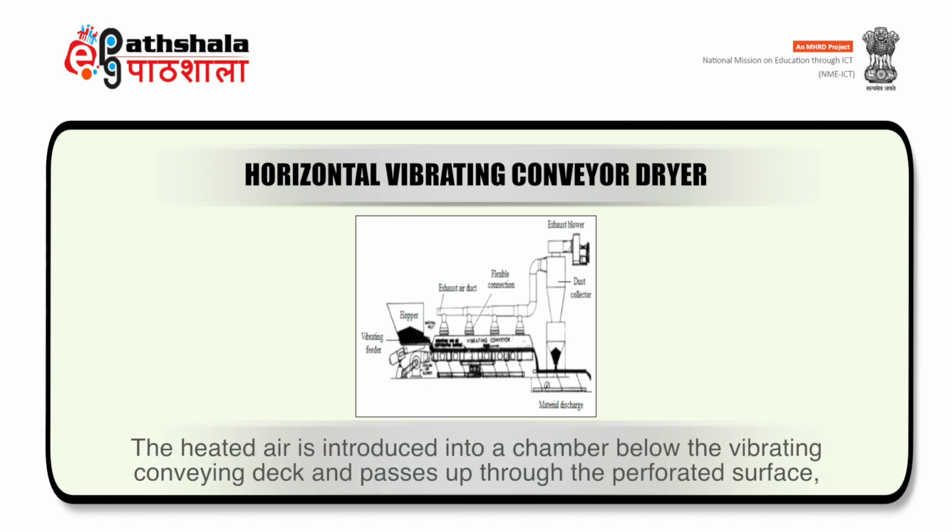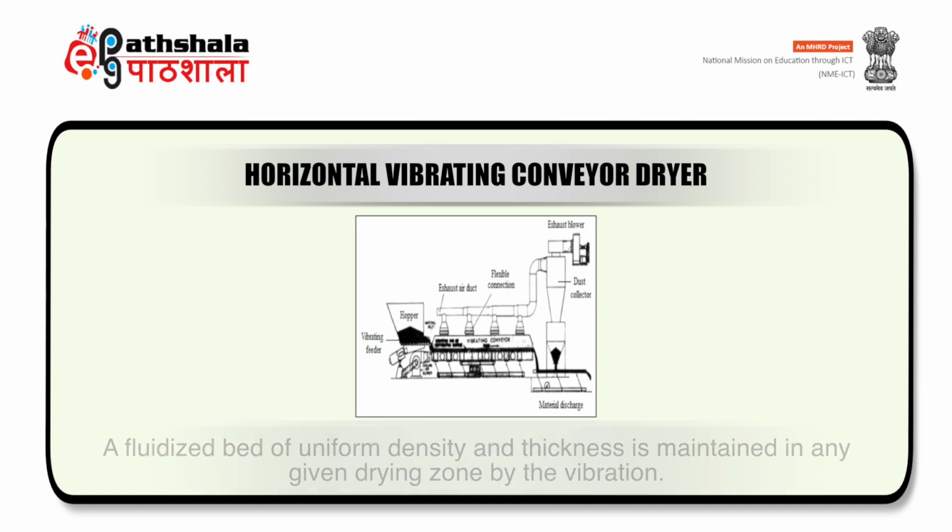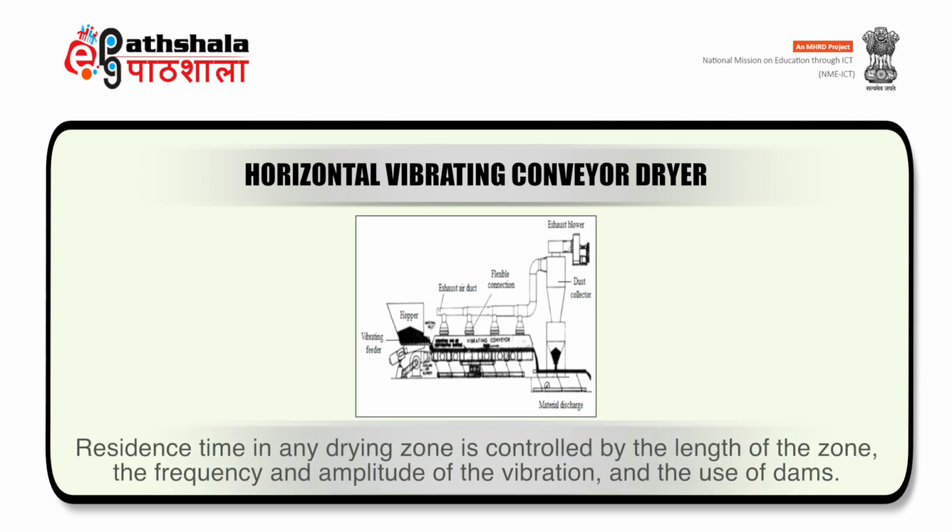The heated air is introduced into a chamber below the vibrating conveying deck and passes up through the perforated conveying surface, through the fluidized bed of solids and into an exhaust hood. A fluidized bed of uniform density and thickness is maintained in any given drying zone by the vibration. Residence time in any drying zone is controlled by the length of the zone, the frequency and the amplitude of vibration and the use of dams.